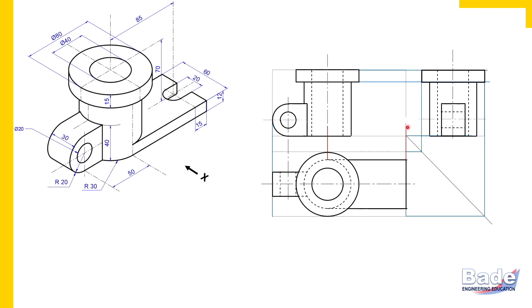So 12 millimeters to be measured to draw that strip. So this is that rectangular strip, 12 millimeters. So this rectangular strip like surface now is ready. But yes, you have guessed it properly. Two visible edges don't intersect, so correction is required. So watch here.